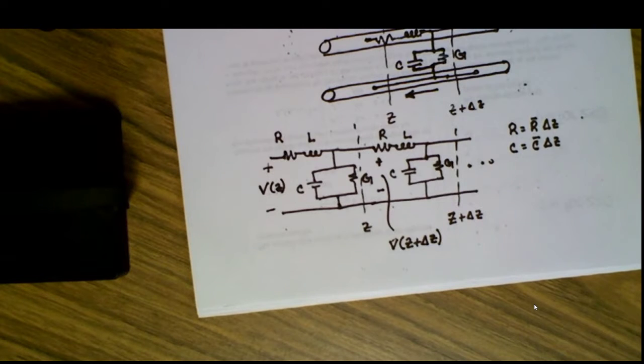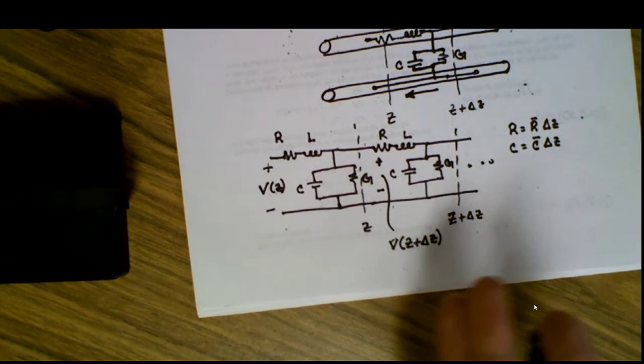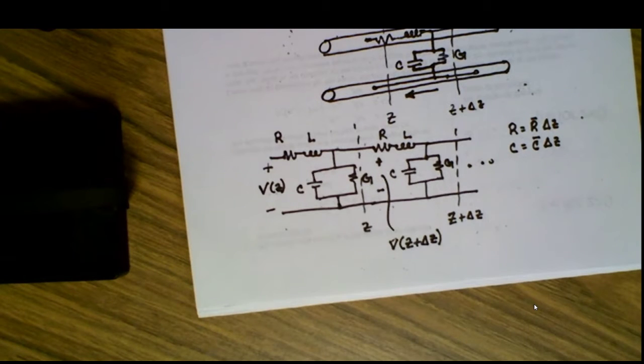That implies that the voltage drop between the end of the wires and any intermediate position between the wires is not going to be the same, except for in DC when all transients have died away. This is the cause and effect relationship that Einstein says it takes time for a signal to propagate. And in these geometries, that time can be shown to be equal to the speed of light.